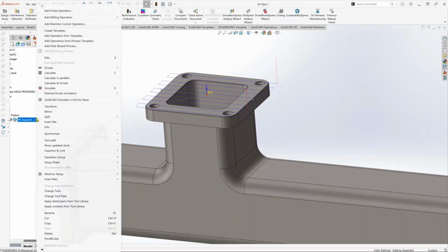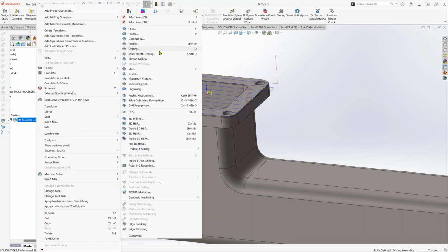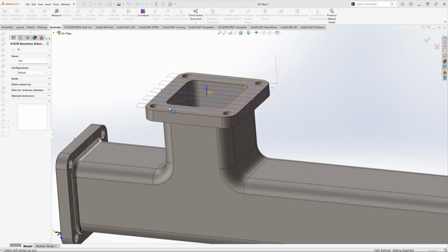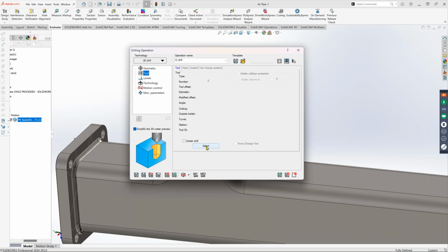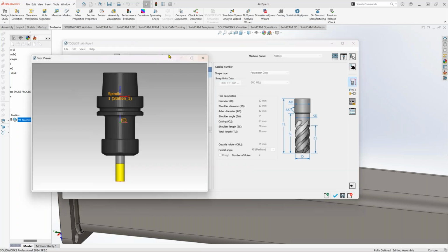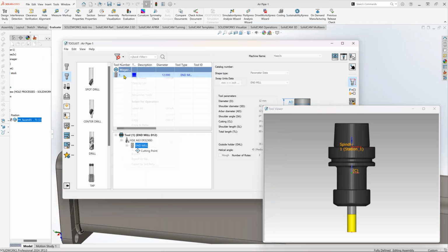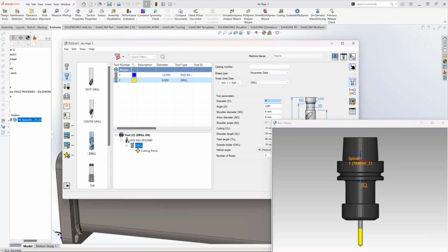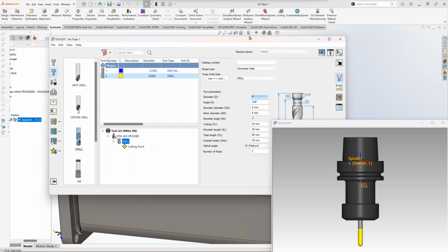You have a toolpath. I will also add drilling. Okay. And select here, I will copy the same tool to keep a holder. Okay, so I will copy and paste. I will hold the Alt key and drag a drill here. So it exchanges the item to drill. Okay, I will change it to 8 mm.